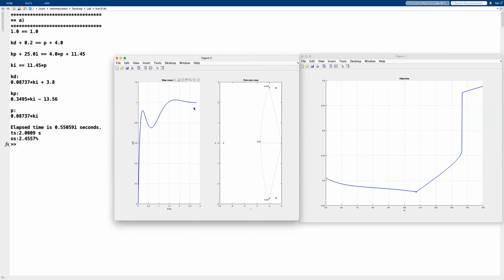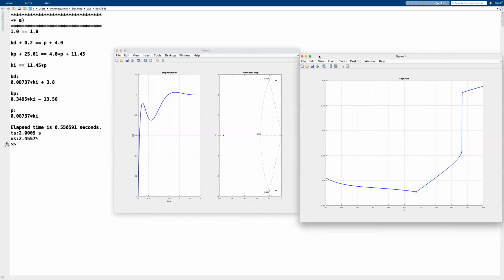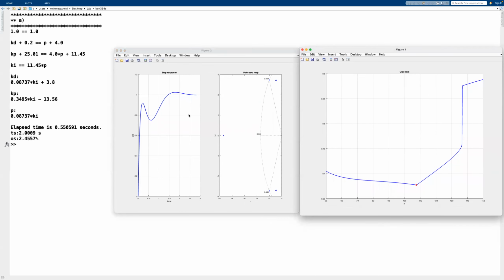The downside to a first order behavior is that it doesn't overshoot, and the second order behavior just gives us that. And here it seems like we're failing in that sense. It has this weird interaction, and we're not happy with it if we are designing a system that should be controlled with dominant pole placement. So I hope that I could give you the clear picture here. This dynamic is a weird behavior. We don't want it for most of the time when we're using dominant pole placement.